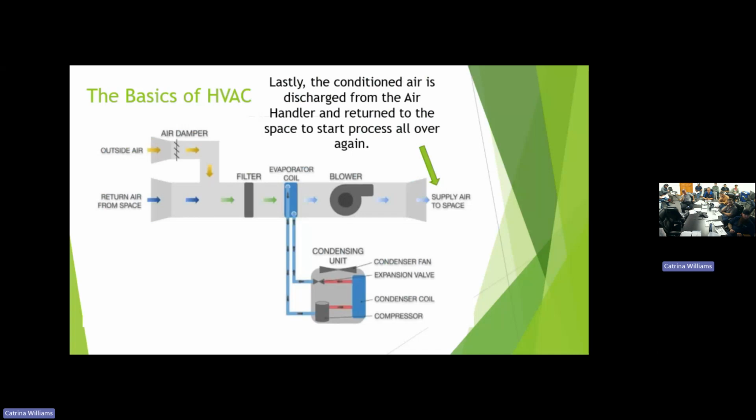That's how we maintain a temperature in any enclosed space. So just these little BTUs going from here to here, exhausting out because of the coil, and coming back to pick up some more of those BTUs and take them through the system again, over and over. That's our basic air handler, how they work, and the basic components you're going to see.